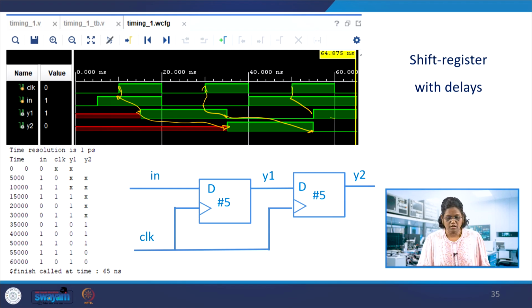So only that to be noted: wherever the clock itself is delayed, the delayed evaluation causes the clock to delay. Otherwise, when there is an immediate assignment, it would form parallel flip flops. Otherwise, if it is a non-blocking assignment, that would form a shift register of the flip flops.